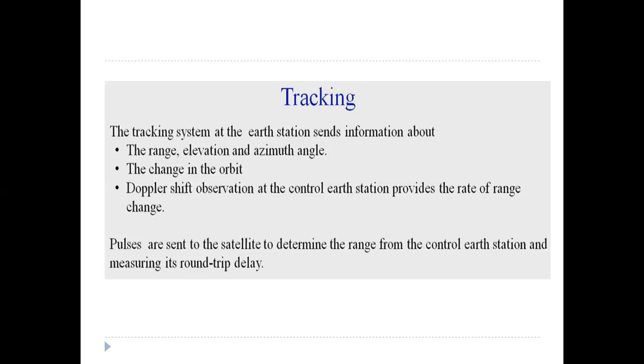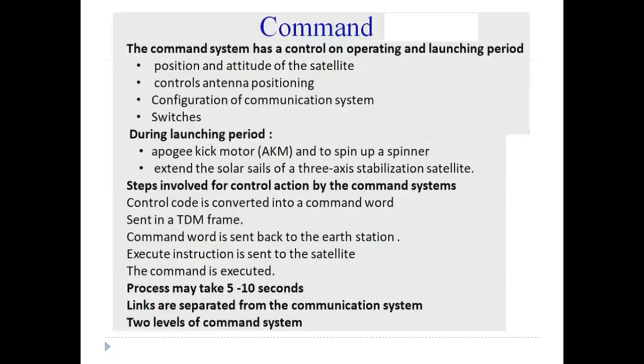If sufficiently high frequencies are used, perhaps even the carrier frequency, range can be measured to millimeter accuracy, and the technique is similar to that used in a terrestrial tellurometer and in aircraft radar altimeters. Command. A secure and effective command structure is vital to the successful launch and operation of any communication satellite.